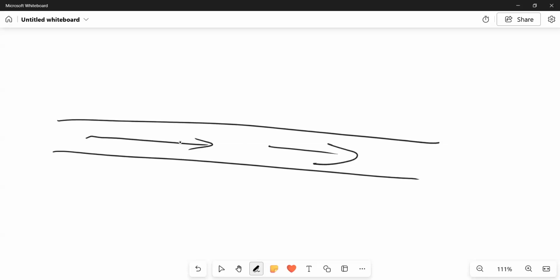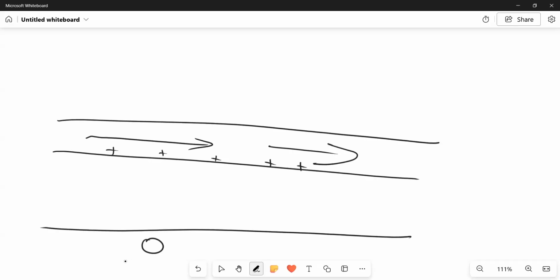Over time, that fluid flowing through the pipe can build up a charge inside there. And what can happen? Because this pipe is now very charged up, out here let's say the potential difference is zero, and down here is positive. You can have a spark jumping across.